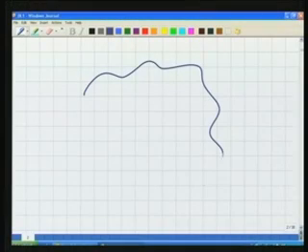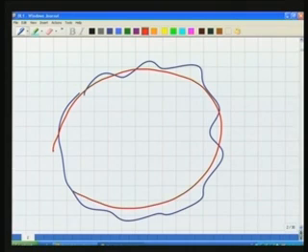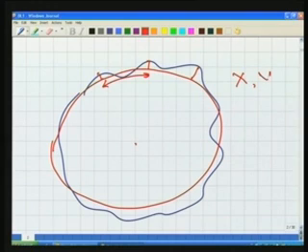So what we did for that, we considered that for our earth, if we can fit an ellipsoid, this is an ellipsoid which is fitting best to the surface of the earth. Now this is an ellipsoid for which we know the mathematical equation, and what we can do, we can project our points on the ellipsoid. So now the distance between these 2 points is actually the distance here in the ellipsoid. We know the equation of the ellipsoid, so we know the characteristics of the ellipsoid. So we can use the ellipsoid for measuring x and y.